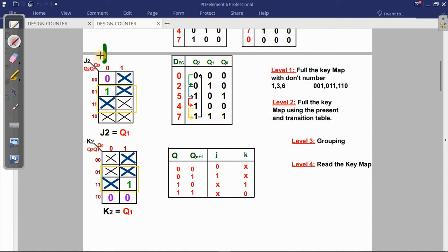We have 2 columns, this column 1, this column 2, and then we have 4 rows: row 1, row 2, row 3 and row 4. What happened? My group is only on row 2 and row 3, but in columns it is on both columns, column 1 and column 2. So my group is on column 1 and 2, not only this side. So we're going to read here. You must know in the K map, 0 cancels 1. If you have 0, 0 cancels 1. Like in our case, let's read Q0.